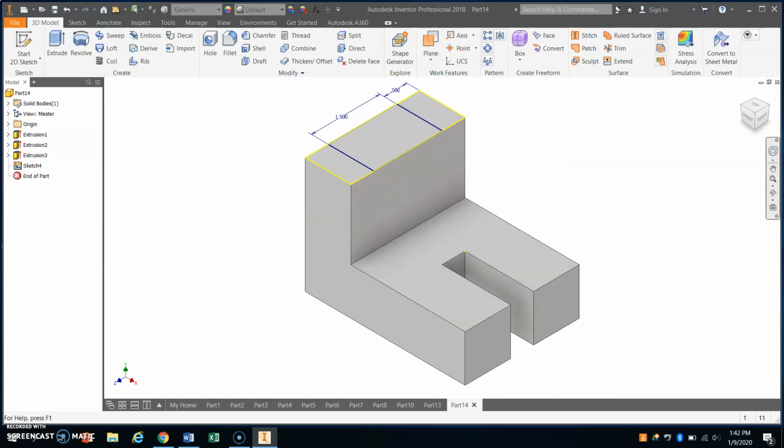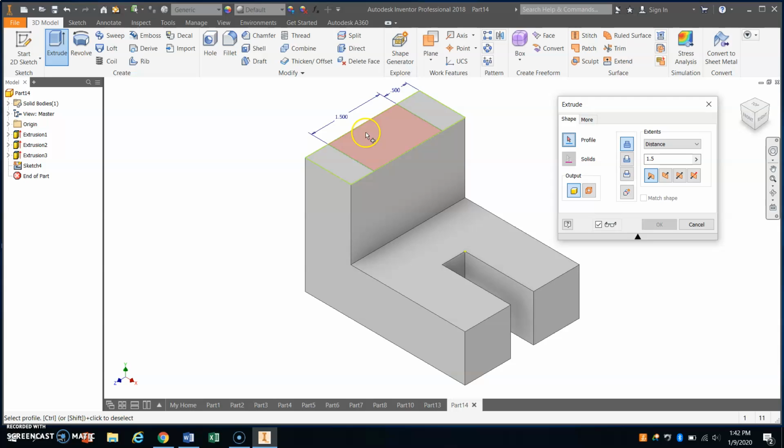Finish the sketch. I'm going to go to extrude. I'm going to grab that part right there. I'm going to cut. Now, if you are having problems grabbing just that center rectangle, hit the back arrow. Make sure you hit the back arrow. Don't go to Start New Sketch. Go to the back arrow into your In Sketch. And as we talked about in the last video, you want to highlight one of these yellow lines that's not connected to that rectangle and right-click on it once you're over top of it and delete that line, and then do it up here too, so that the only enclosed geometric shape is just that rectangle.